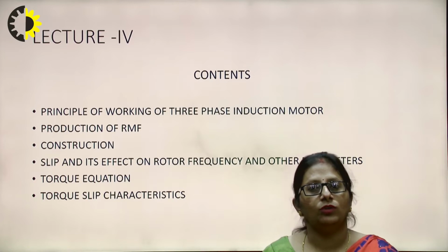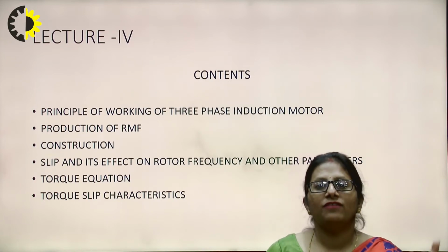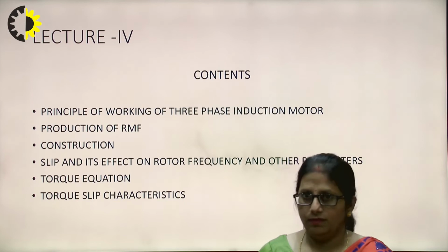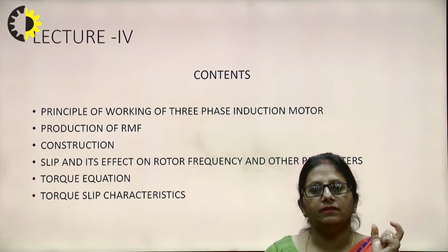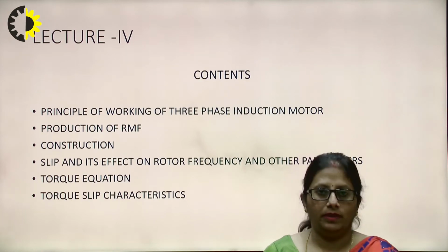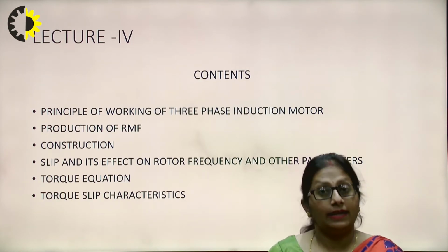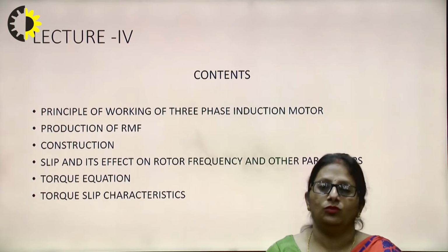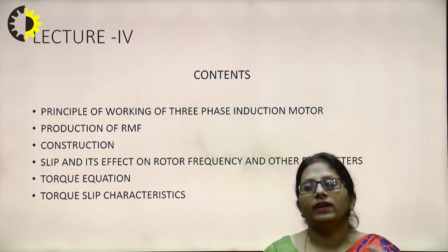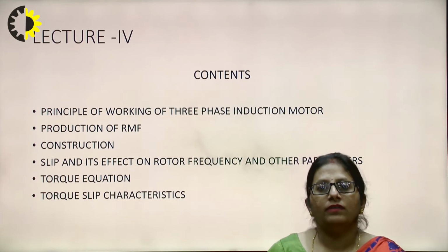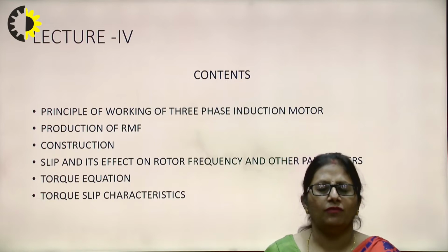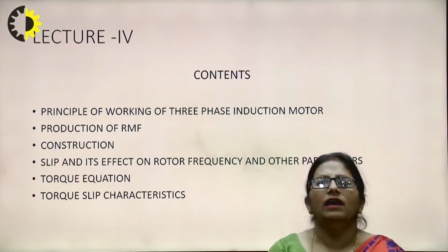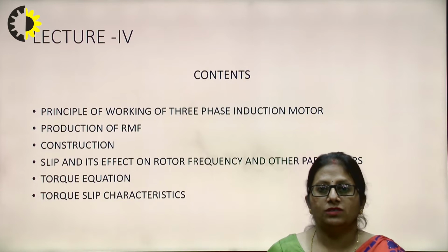Likewise, the DC shunt motor is characterized by a fairly constant speed. There is a very minimum amount of decrease in the speed with the load, otherwise it is fairly constant. It is a constant flux motor as well. So it finds its applications where the speed required is fairly constant: fans, blowers, drilling, milling, pumps.